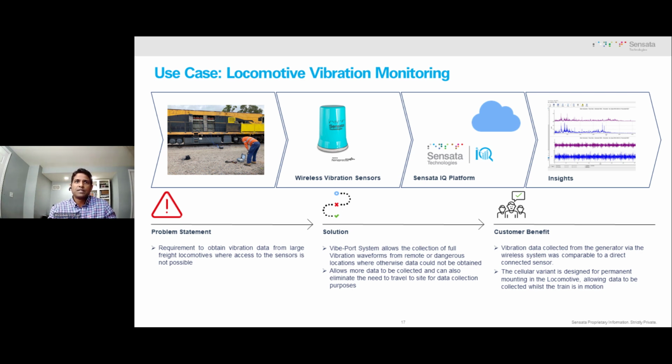The existing tools such as hot bearing and dragging equipment detectors have been in place for a considerable amount of time, but unlike vibration monitoring, these units detect components that have already failed. So a vibration sensor can monitor specific components and provide pre-failure notifications, leading to long-term cost savings. The rail industry can benefit a lot from this, and we have proved that in practice through the vibration monitoring system, where we had a reduction in failures and an ability to better schedule the maintenance of critical